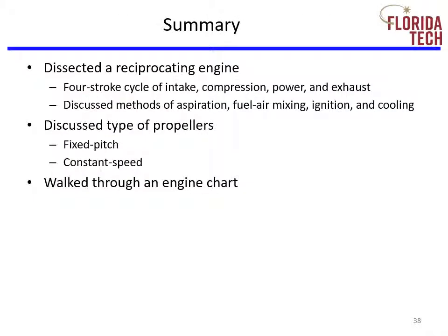In summary, we dissected a reciprocating engine. We examined the four-stroke cycle of intake, compression, power, and exhaust, and we discussed methods of aspiration, fuel-air mixing, ignition, and cooling. We also discussed types of propellers. Basically, there's fixed pitch or there's constant speed. And then we just finished walking through an engine chart example. This concludes the module for reciprocating engines.